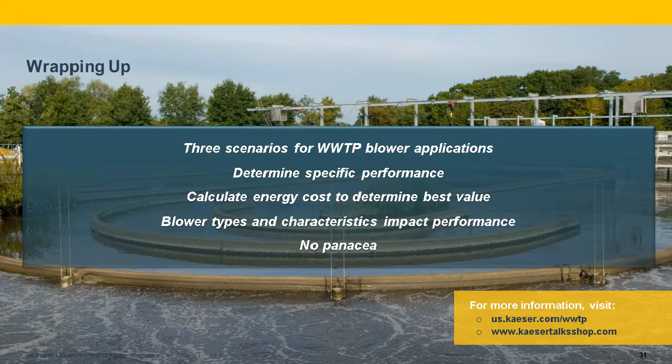Then we looked at types of blowers and related their operating characteristics to the applications. While some types may deliver better energy performance in one scenario over another, you have to look at the specific performance in the context of the expected operating range to compare and assess the energy consumption. There is no one type or brand that is best for every scenario.